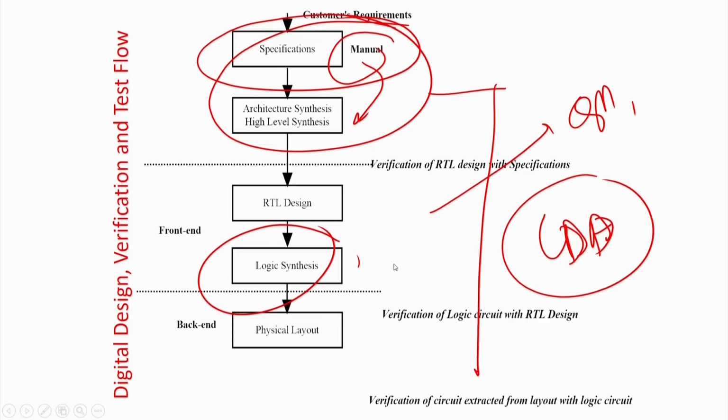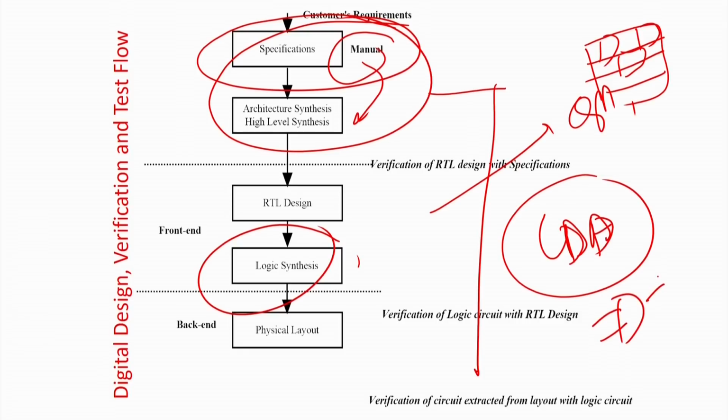transistors. In that case also you should have very good placement and routing algorithms, because in placement and routing, basically you have the circuit die and you have to place your gates in all the places and make interconnections. When you implement, a gate will not look like this; a gate will look like a rectangle, and there are a lot of rows in a die. You have to put the gates in the proper positions in a minimal amount of area, so that you can do the interconnection. You can look at any standard backend architecture; we will also slightly cover this in this course, and basically you are going to get a physical implementation of that.